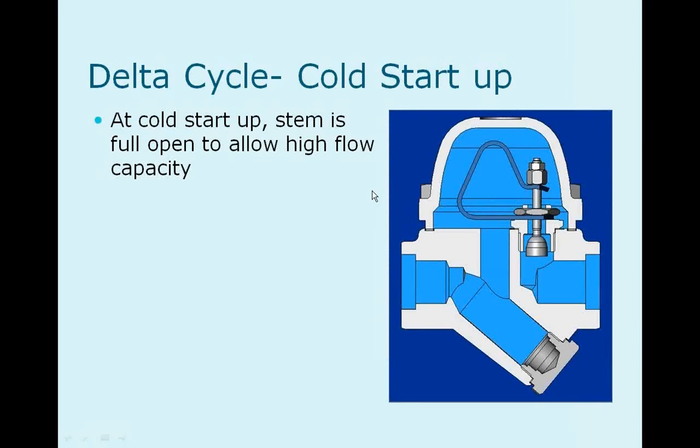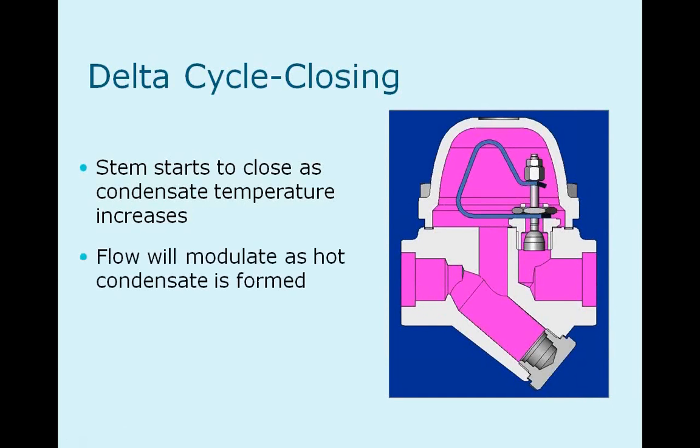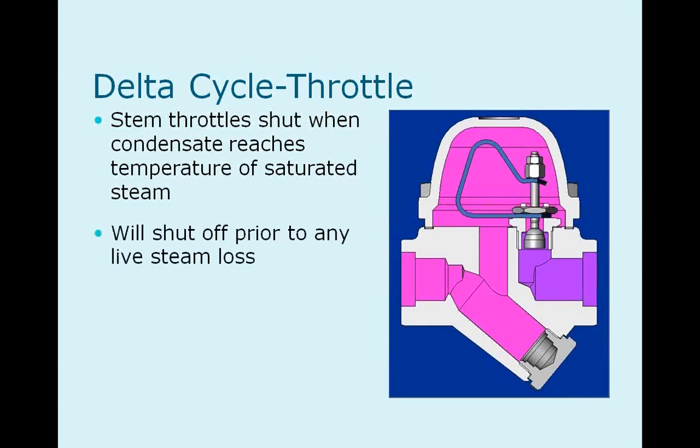The bimetal that operates on temperature and pressure, again, just showing you how that works. So the pressure goes down and pushes down on the orifice to open it. And it is a modulating trap, but it will close off if steam gets in there. That will actually expand this element far enough that it will close if it gets hot enough. And the idea here is, unlike the disc type or the bucket, you don't pass any steam with that type of design.